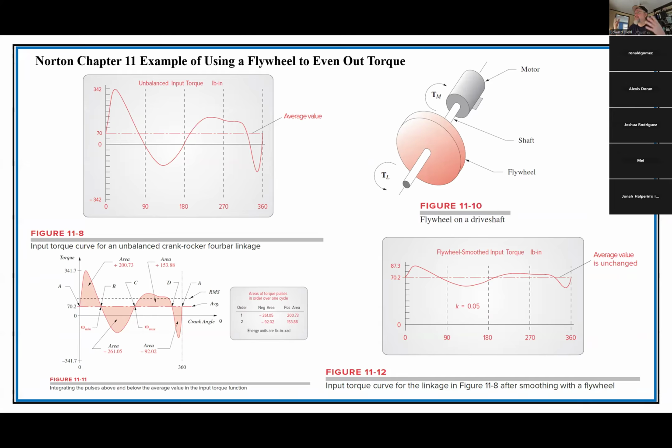But you want to try to match that to a motor or pick a motor that would be sufficient for that torque. Well, that's really kind of difficult when the torque is all over the place. Having a flywheel will definitely help in real world applications. So you could see adding a flywheel, if done correctly in here, you could get this. These graphs are the same, and you could take a look at the scale on here.